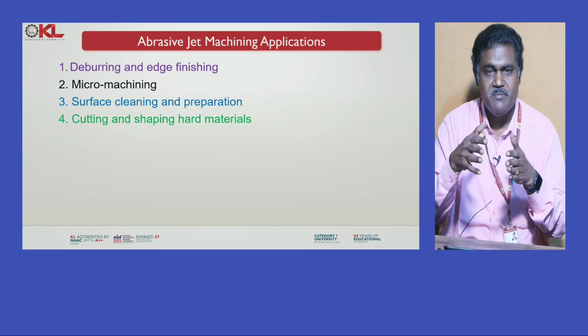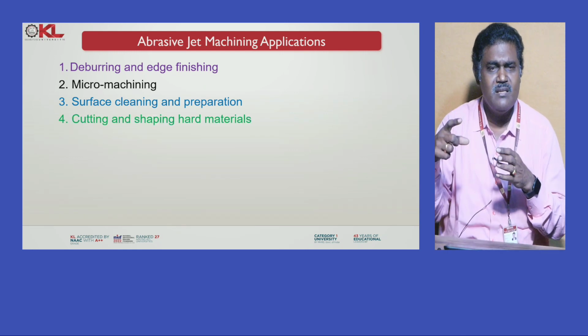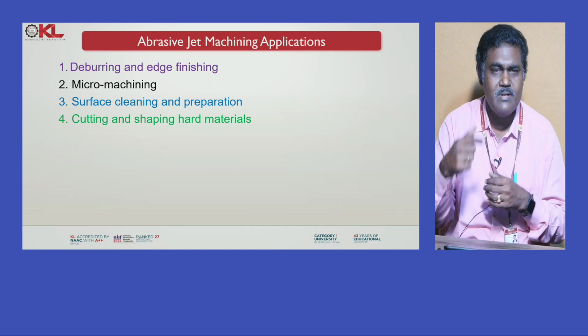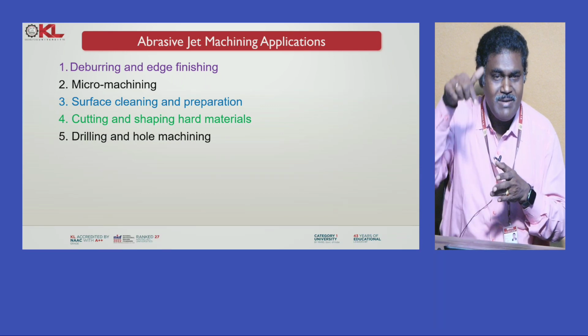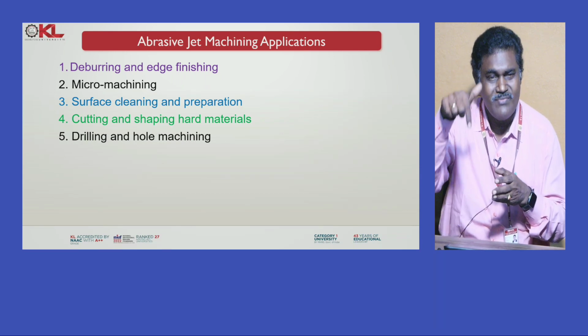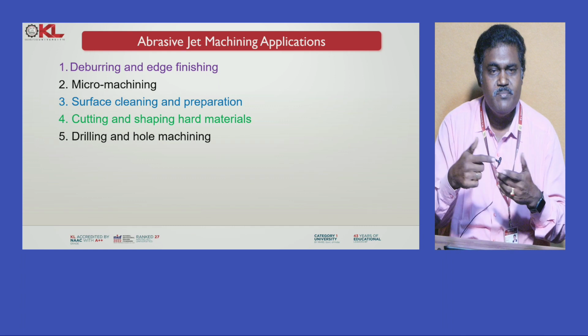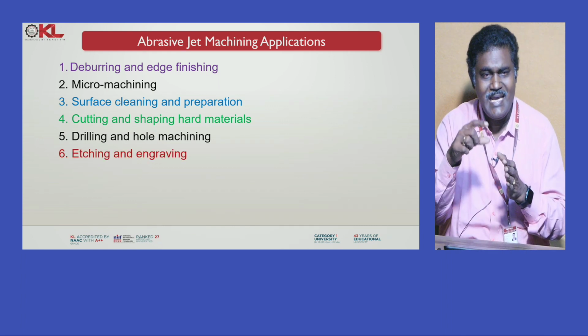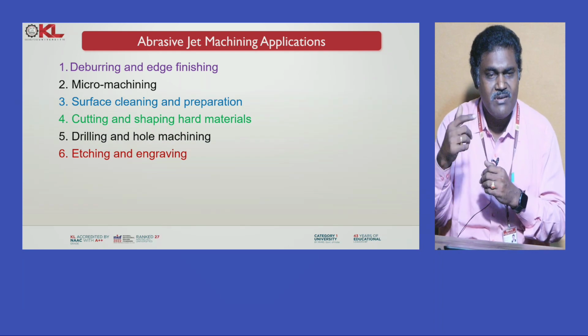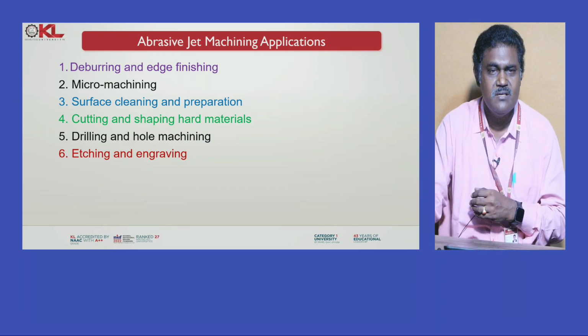Then cutting and shaping hard materials. Very hard materials you can easily cut using abrasive jet machining. Drilling and hole machining. You can drill holes in hard materials, which is possible using abrasive jet machining. And etching and engraving. Etching and engraving operations are also possible with abrasive jet machining.